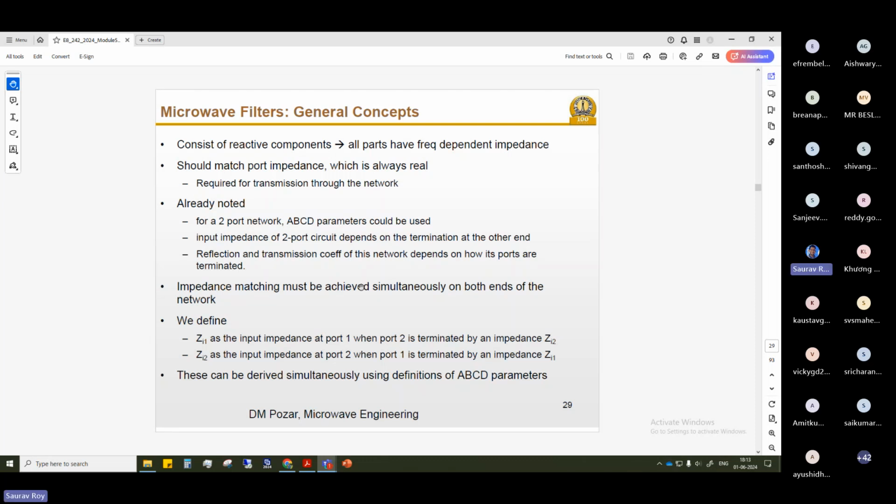Whatever you used to build circuits or filters with normal R, L, and C components, you cannot purely do that in microwave frequencies with simple RLC, because in high frequencies they will definitely bring out extra parasitics and other effects. So that will lead to the change in filters. So how do we generally replace the RLC in microwave frequencies?